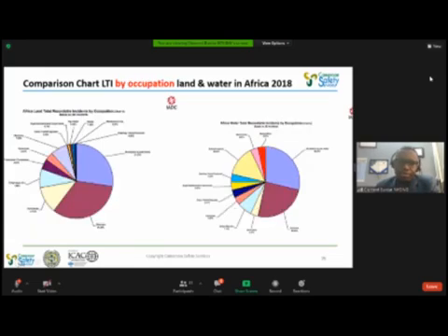By occupation, who are the people most exposed to lost time injury, who have injuries most often? Floormen, the roughnecks, those who are working directly on the rig floor, connecting pipe, disconnecting pipe, BOP maintenance. The roustabouts are second after the floormen because they are also in charge of maintenance on the rig, so they get into contact with chemicals. They do sanding, they do blasting. They are involved in lifting operations. So they are one of the people most involved in injuries.